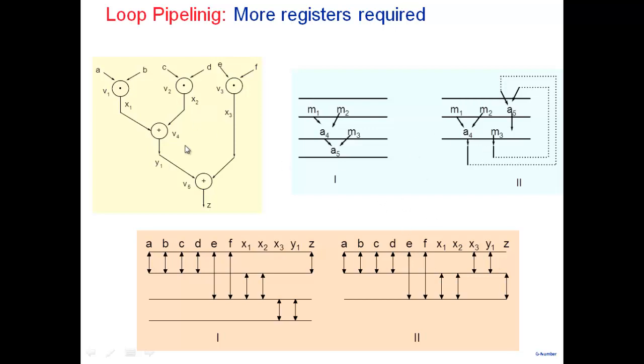So in general, when you pipeline a system, it's understandable, because what is pipelining? You're not only processing the present data, but the previous data also. So it's obvious that I need some storage for previous data also. If you're doing simultaneously present data and past data also, some storage is required. Yes, so you'll end up using more registers, but it may be worth the price paying.